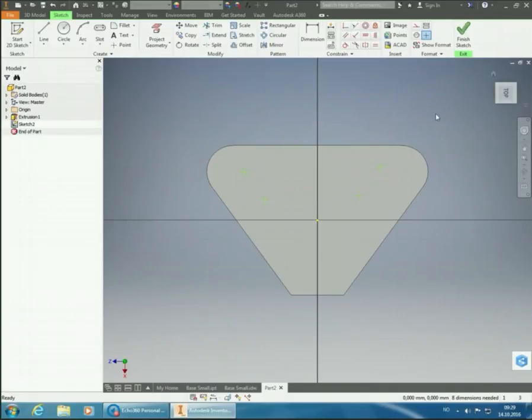And you can see that they're green because they're not locked into place in any way now. So I've got 4 green points, and now I need to use dimensions to place them in the correct locations. So I go up to the dimension function, and I'm going to use the end of my plate to give the heights of the holes first.